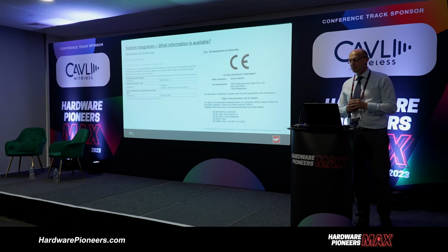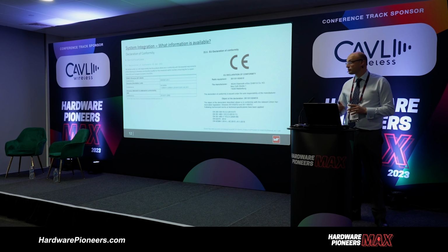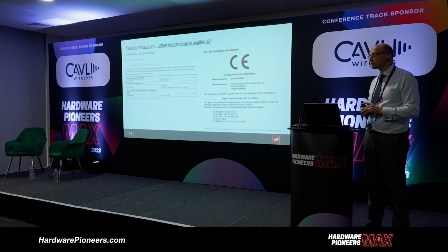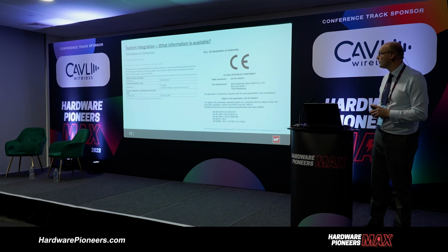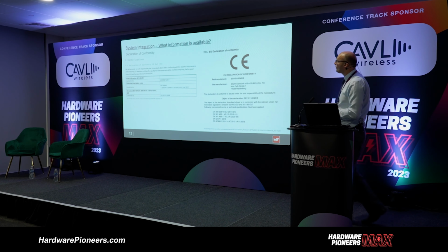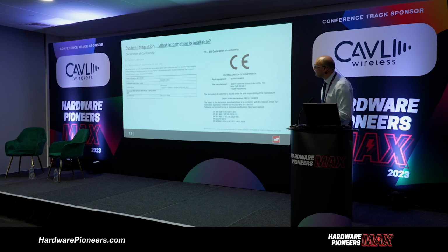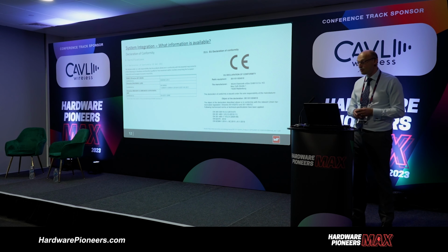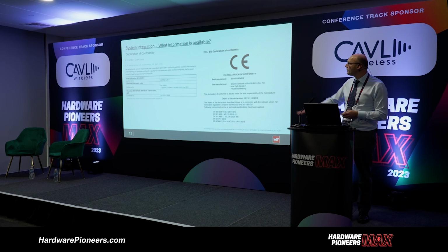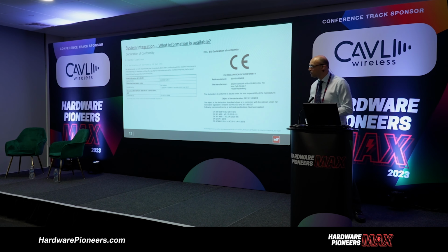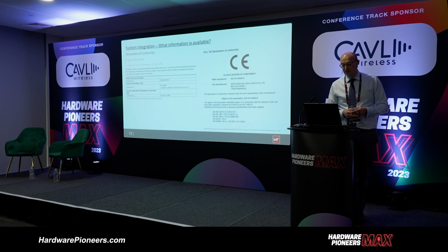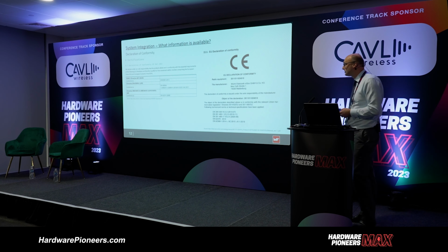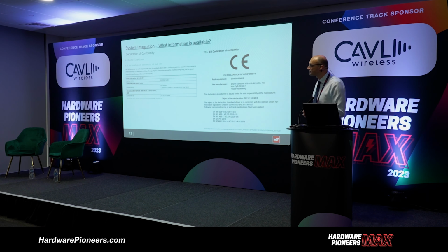Well, what you can start to do is actually look at what, say for example, the radio module manufacturer is providing with their radio module. So on the left-hand side, I've actually found the declaration of conformity. It is publicly available for that particular Arduino unit. And we can see what they are basing their CE marking on. So in this case, they're basing it on the RoHS directive, which is a requirement for CE marking.